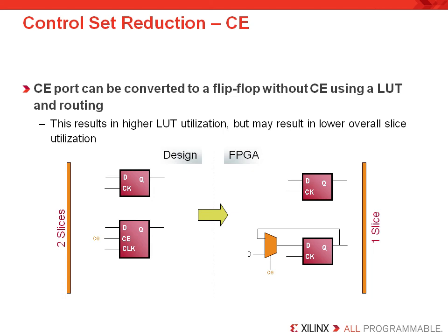So the caveat here is we can pack these 2 registers in the same slice because now the control sets are identical. The caveat, of course, here is we lose some LUT inputs to this second flip-flop. So it's a good and a bad thing, but the key thing is if we build a synchronous set or reset or a clock enable, we want the tools to have this ability because it can improve our device utilization.